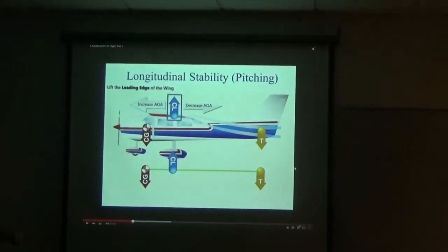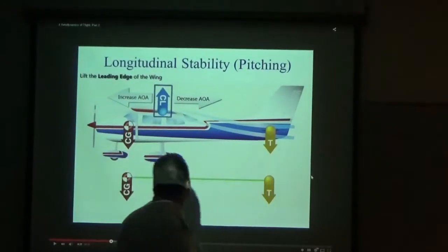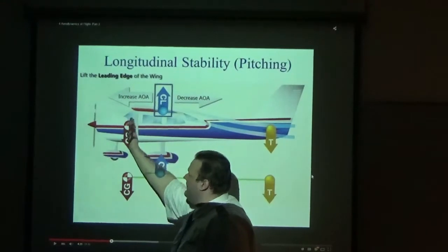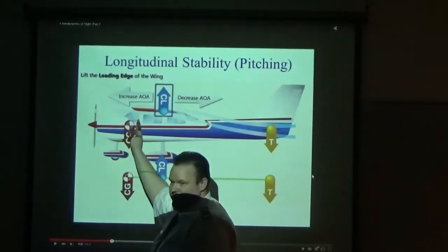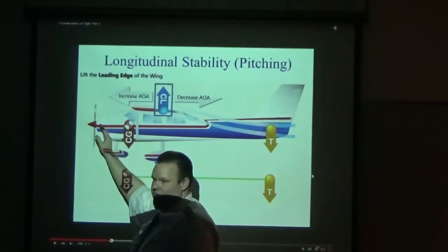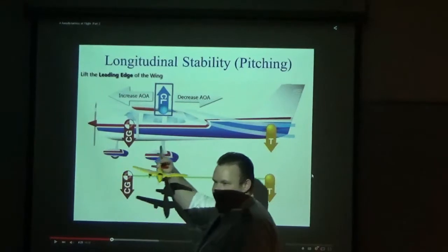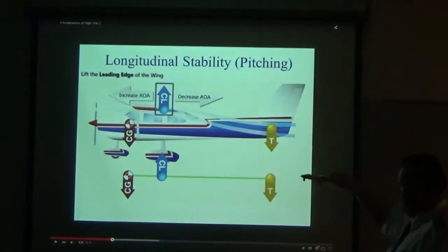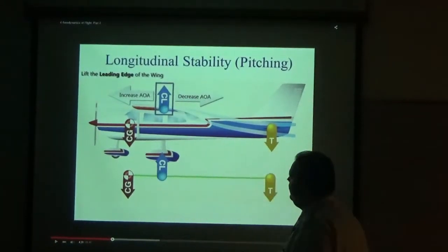Like here's the Skyhawk right here, which is a typical trainer. This is what I fly in most of the time. You see where the center of gravity is already. It's right there at the firewall for the engine. So it's really hard for something like a trainer to get a forward center of gravity where it's just so heavy it's just going to stay like this, which is obviously hard to take off on, because you can't, again, pull the tail down enough to get enough lift to pull it up.